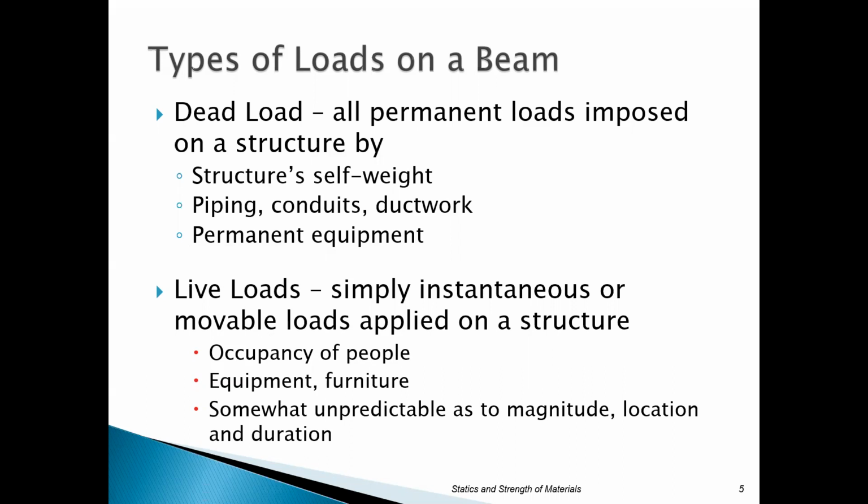And then live loads are just loads that basically move around. They instantaneously give you a load, but that's going to change. So things like people in a building, obviously we get up, we walk around, we move. That's changing. Some equipment's going to move around, and furniture. Things like snow and wind loads are considered live loads because those are changing constantly. Like someday it was very windy. You can imagine on a high, tall building, a lot of those buildings actually sway with that. So a live load's somewhat unpredictable, and you can't necessarily get a magnitude, location, or duration. But they do have to be accounted for at times.